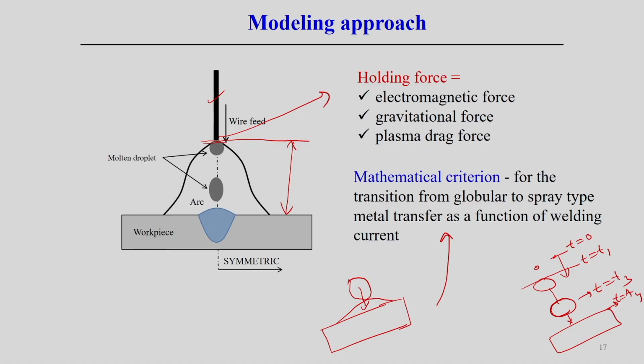So, this way we can divide the different domain subdomains, and within these different domain subdomains we can solve the governing equation associated with each. For example, if we are considering only the heat transfer part, then we can solve only the heat conduction equation during this particular process, maybe at the defined geometry or the defined boundary interaction. Then if there is a need to look into the material flow field also, then we can solve the Navier-Stokes equation, or the fluid flow field we can estimate along with the boundary condition.